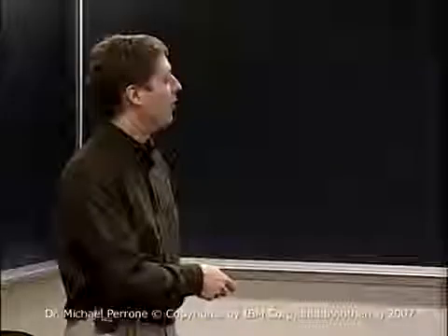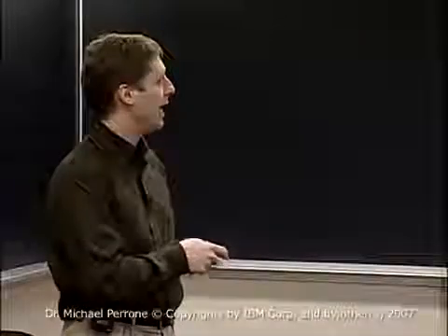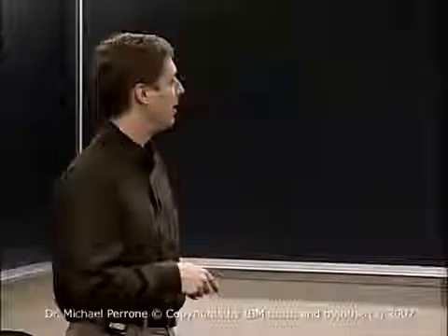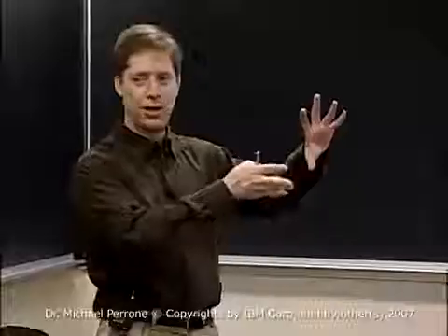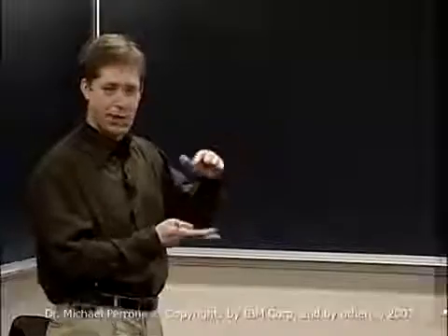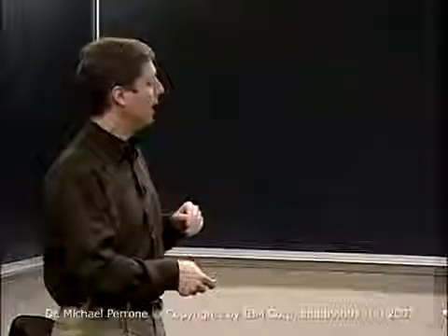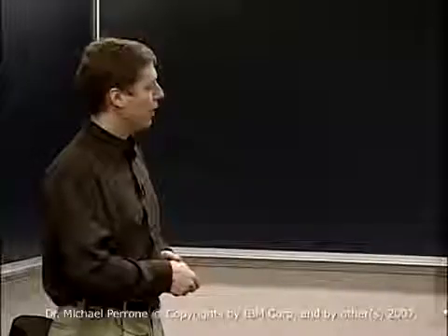Then, once you've done this, you may find that what you originally thought for the complexity or the layout wasn't quite accurate. So you need to then go do some additional rebalancing. Maybe change your block sizes, that maybe you had 64 by 64 blocks. Now you need 32 by 64 or 48 by whatever. Some readjustment to match what you have. And then you may want to reevaluate the data movement. And then, in many cases you'll be done.